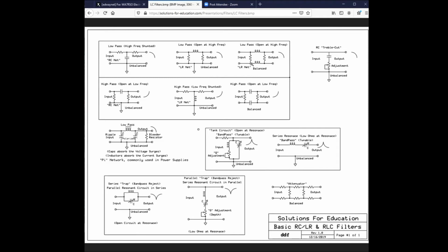At the Space Center, when we were taking signals off of the shaker table, these signals are down in the millivolt range, and they're like 80 yards away. And as the cabling, or I should say the data, is shipped up to us where we're analyzing it, you can pick up a lot of signals that you don't want to come into your situation.